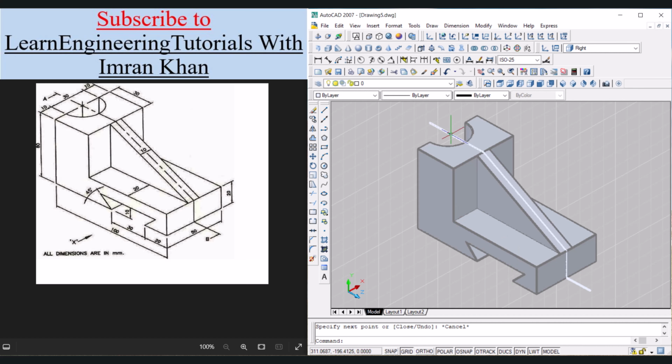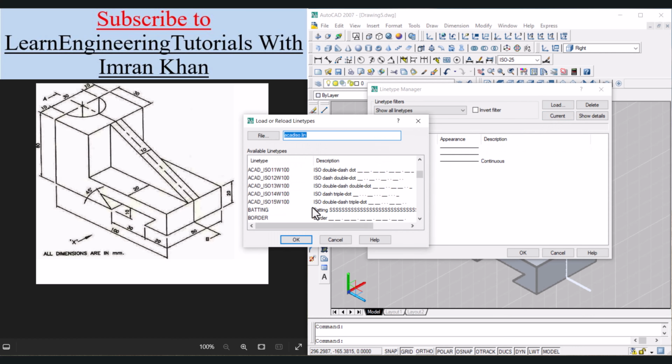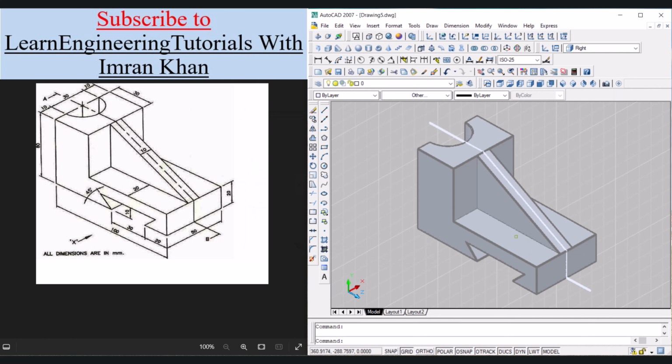Now we have to make these lines as center lines. So we will go to the property menu, click on this second box, and here we can see continuous only. Let's load center line here. So click on load, search for C, center, click on OK, click on OK. So now select these lines.